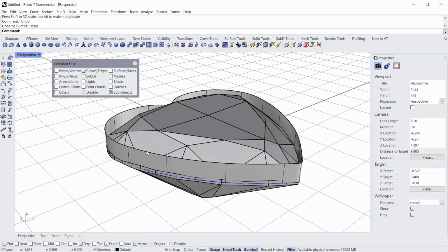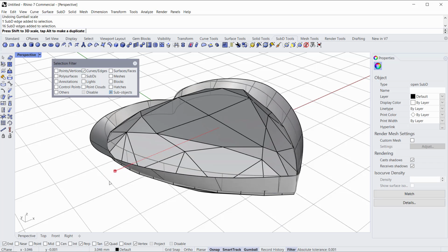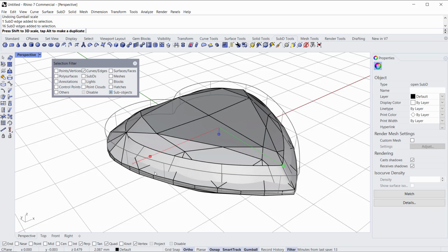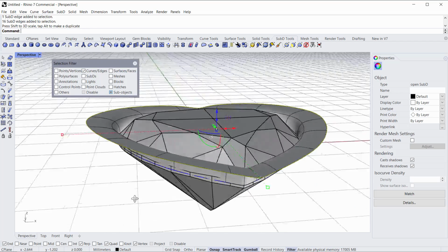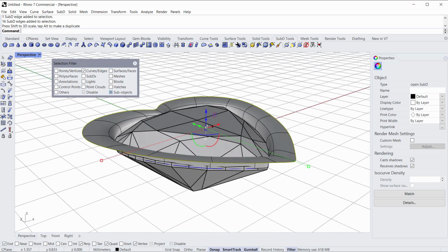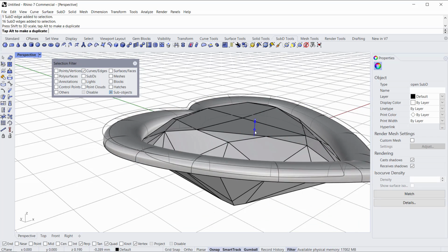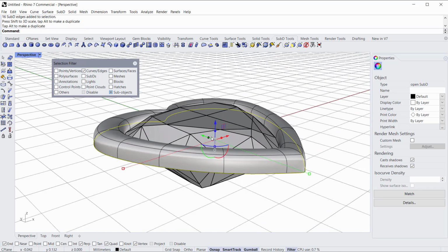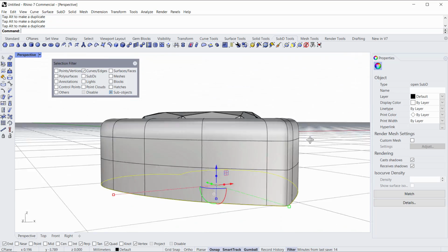So I'm going to back up. I'm going to double left click. I'm going to start to edit this. I'll pull on it. I'll hold Shift so that I get X and Y together. And then I'll add Control so that we can extrude. The other way we can extrude when we're going vertical extrusions here is we can use these dots that are on the gumball. Since our edge is still selected, we can grab this blue dot, which is the Z-axis here, and add a couple rows going down.